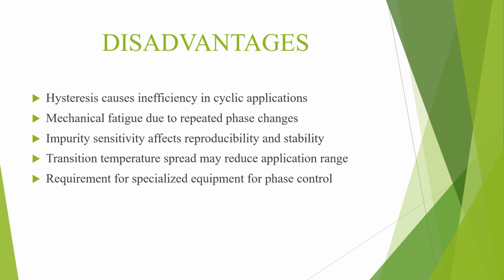Disadvantages: hysteresis causes inefficiency in cyclic applications, mechanical fatigue due to repeated phase changes, impurity sensitivity affects reproducibility and stability, transition temperature spread may reduce the application range, and requirement for specialized equipment for phase control.